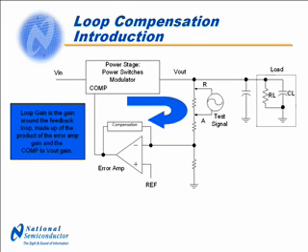One big advantage of current mode control is the robustness and high performance of the loop dynamics. Current mode control can be modeled as a single pole system. Only the output load resistance and capacitance affect the loop characteristics. The inductor acts as a current source and does not play into the loop dynamics. Another advantage of current mode control is that input voltage changes are immediately compensated for, referred to as feed forward.